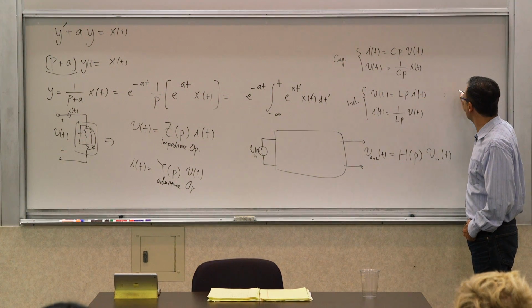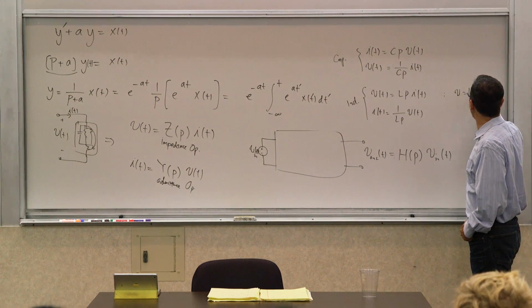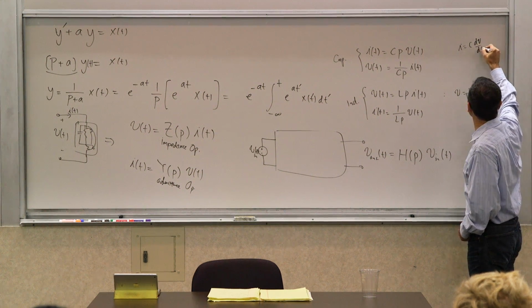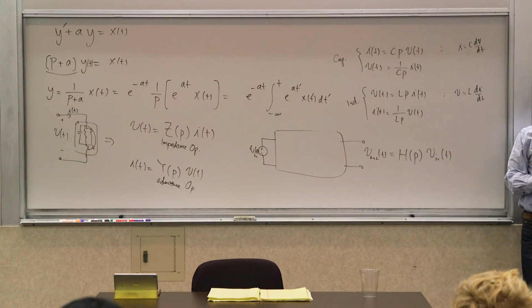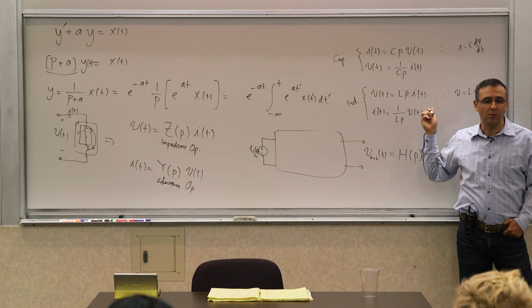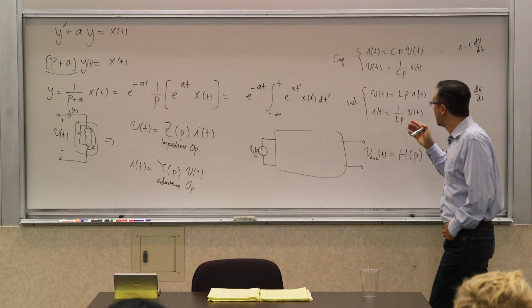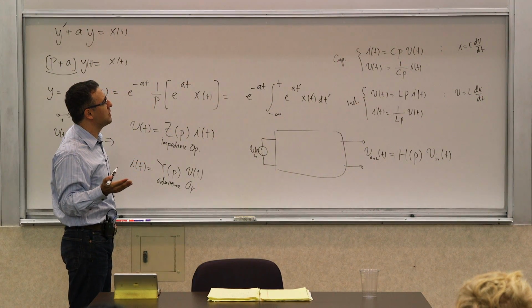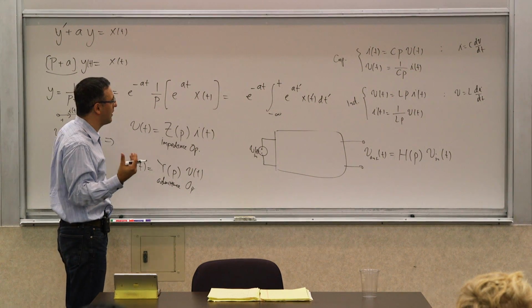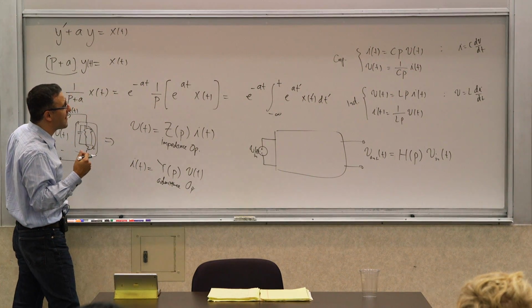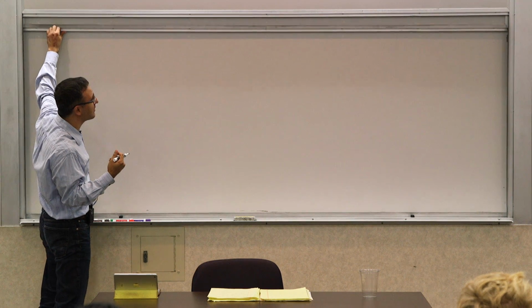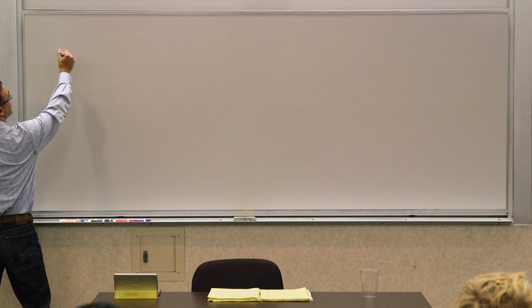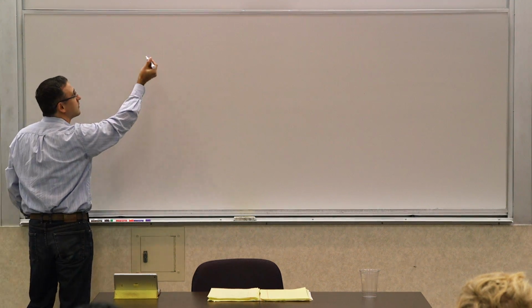I mean, this is basically equivalent to saying V equals L di/dt. This is like saying I equals C dV/dt for a capacitor, and so on. That's a shorthand notation for that. But this, combined with the fact that at least for these elements they behave algebraically, has an important corollary: if you have inductors and capacitors in your circuits, you can treat them like resistors whose values are these operators, Cp, 1 over Cp, or Lp.